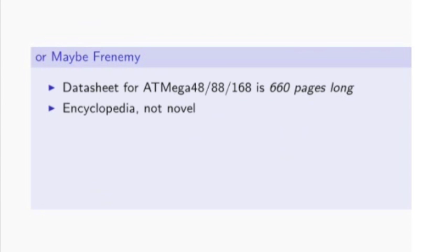You don't want to start at the beginning and start reading this thing. It'll kill you dead. In fact, I'd say the first 2 pages are a really good read. Page 1's a summary of all the peripherals and abilities. It tells you how much power the chip needs, what its maximum voltages are, all the specs. Page 2 is that pinout diagram where it explains all of the functions of all the different pins. You'll be using page 1 and page 2 over and over.